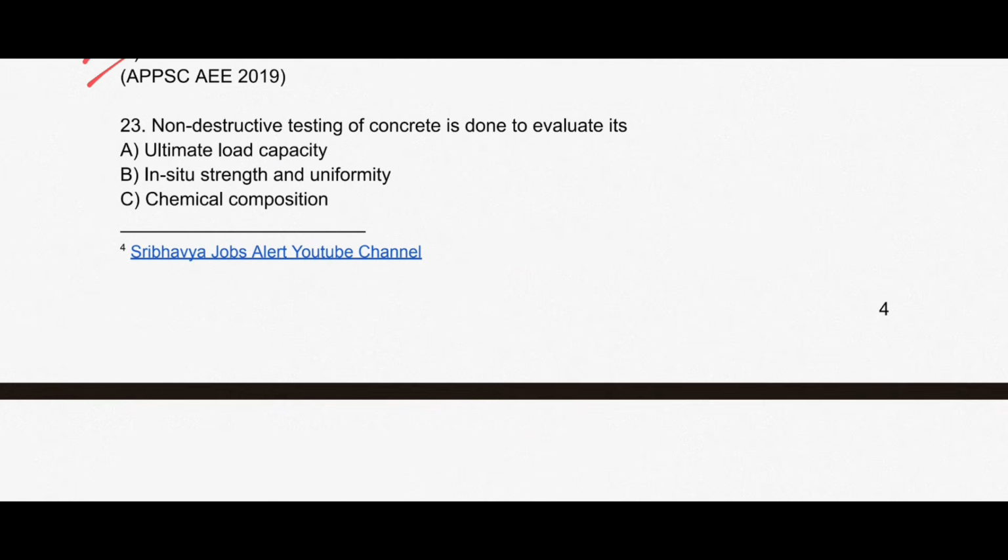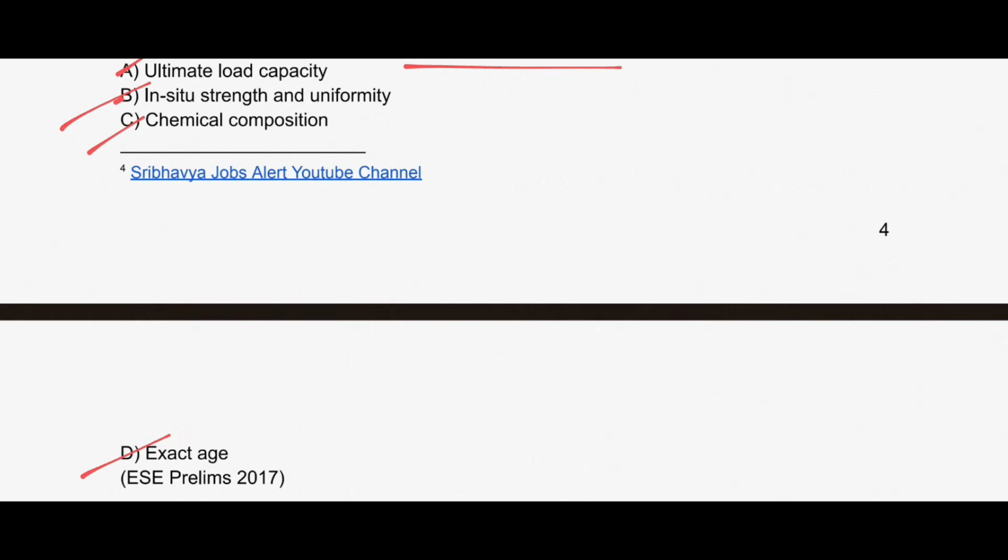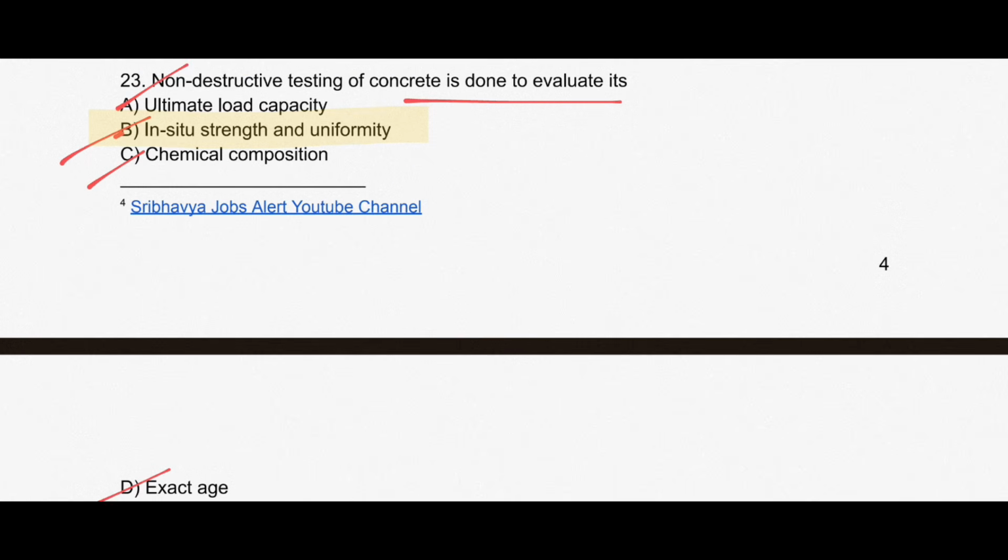23rd question. Non-destructive testing of concrete is done to evaluate its ultimate load capacity, in situ strength and uniformity, chemical composition, and exact age. So the answer is option B, that is in situ strength and uniformity. All non-destructive tests are done in situ. So in order to find the in situ strength and uniformity, we go for the non-destructive test of the